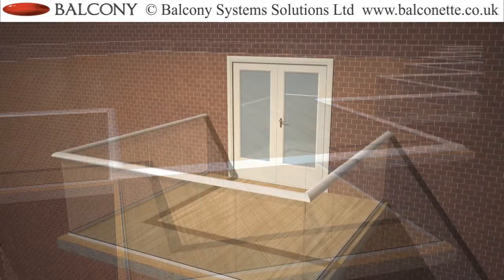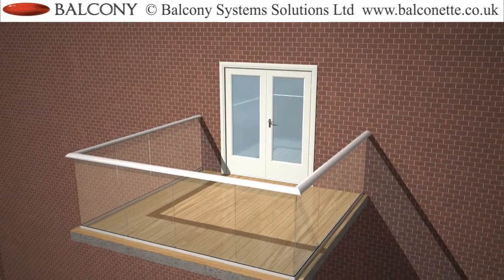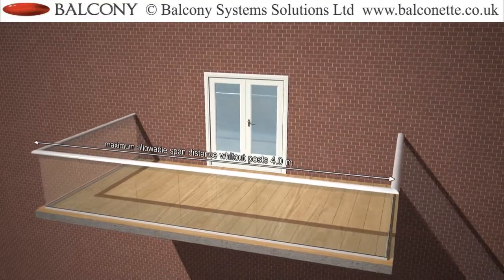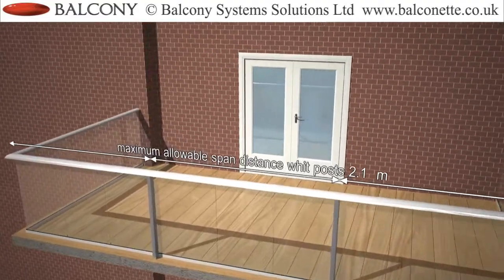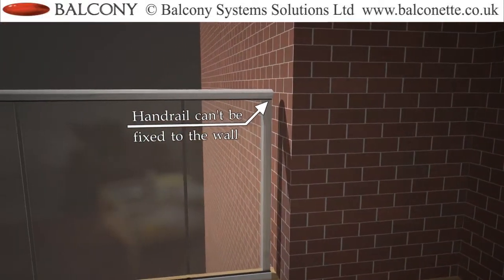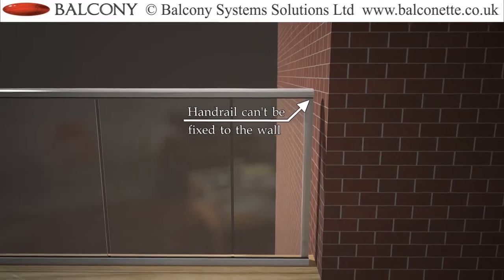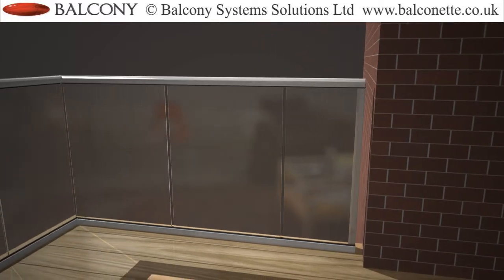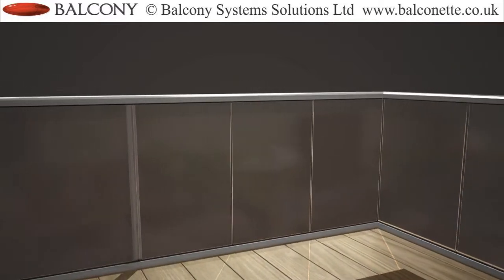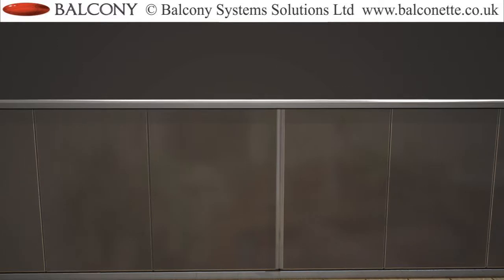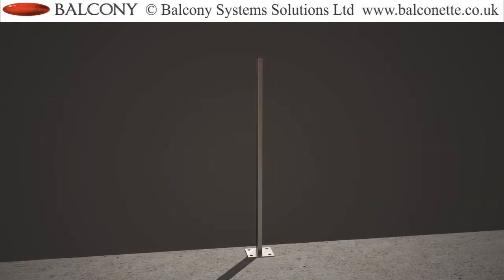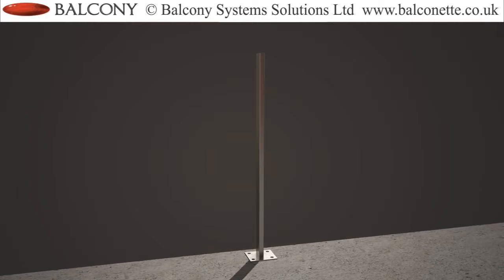Posts are required when one or more of the following exists: when the length of the run is longer than the maximum allowable span without posts of 4 meters, or when the handrail cannot be fixed to the structure or wall firmly at both ends of the balustrade run. When posts are introduced, the limiting factor is the strength of the post, and this is what now determines the maximum post distances allowed. The post is made from a 2-part system: the primary steel post that has a base plate and the cover post.